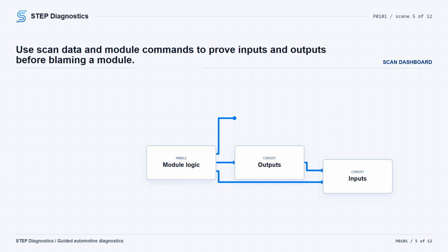Test hardwired and networked inputs. Test outputs, and check for module software updates. If you are checking module switching circuits, use output state control to command components. If the module output works normally, shift your attention back to the inputs instead of condemning the module. Unnecessary module replacement usually comes from incomplete testing, and jumper wires should not be used to feed power or ground directly into module switched components unless the test specifically calls for it.